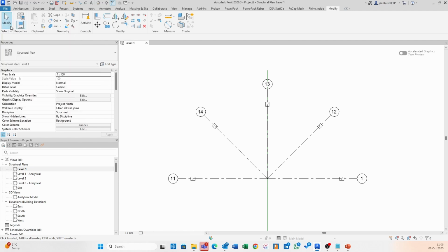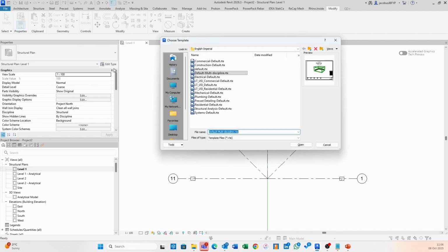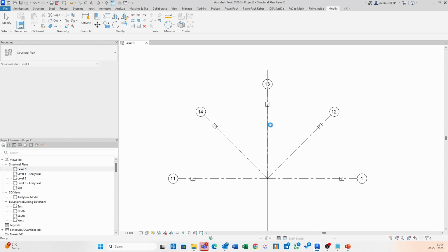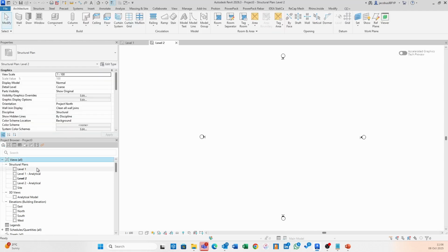So what we're going to do is let's just create a brand new template. So I just want to select a brand new template, and we can then go from there. I usually work with the South African content pack template. That's just the nicest one to kickstart things off with, and a really good one to use as a baseline for any templates that you might look at setting up. It comes preloaded with the South African rebar shapes, which is very, very useful. So just something to keep in mind as well. Installing the South African content pack is really useful and can greatly simplify your workflow.